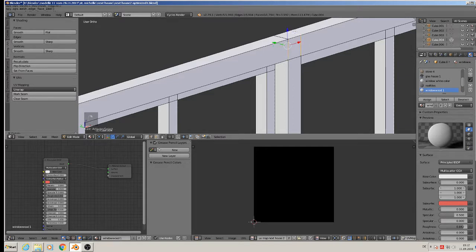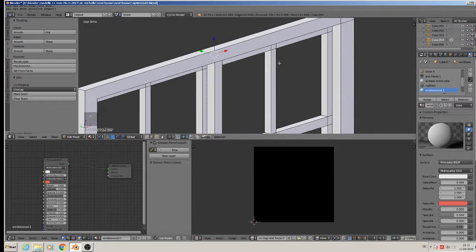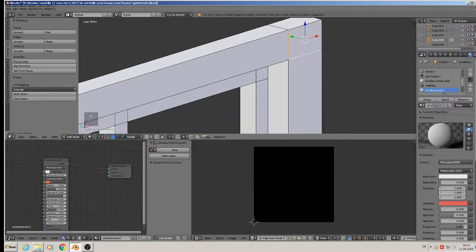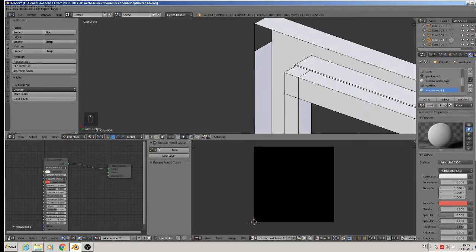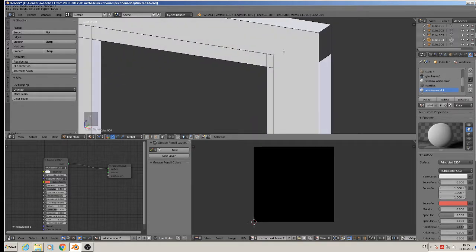Here's the same, that we can dissolve, that we can dissolve, and here on the back, these both we must delete, because we don't want to see them there. They are not there, and that is a vertex, and I don't want to spend vertices for nothing. So I dissolve the edge here, or dissolve vertices,